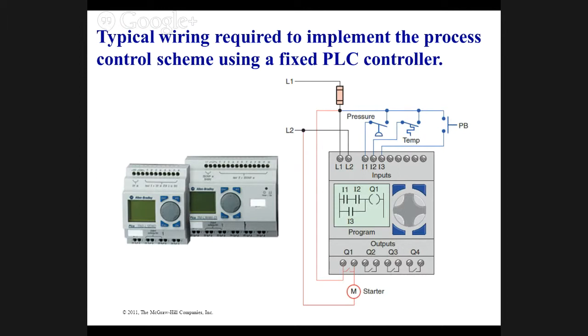You see the jump? How about the output on the Q1? See here, this is the power coming down through here. This is a relay built into the PLC. That's inside the PLC. So each one of these has power in, and then when the PLC tells it to, it's going to close that little switch and send it out. Yeah, that's what that is. That's kind of showing the wiring diagram also.